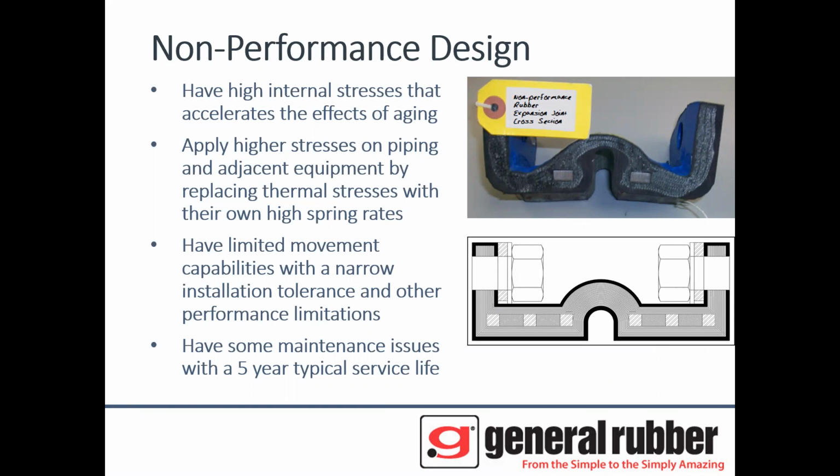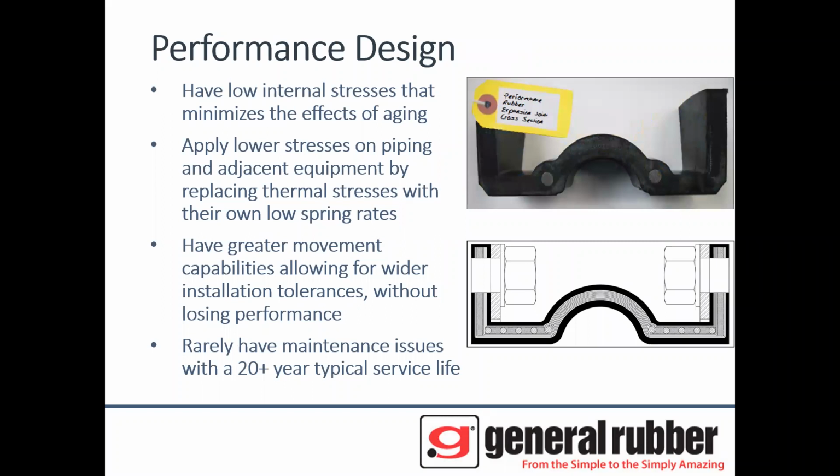They apply higher stresses to the piping and adjacent equipment by replacing thermal stresses with their own high spring rates. They have limited movement capability, a very narrow installation tolerance, and performance limitations, sometimes having maintenance issues and only a 5-year useful life.